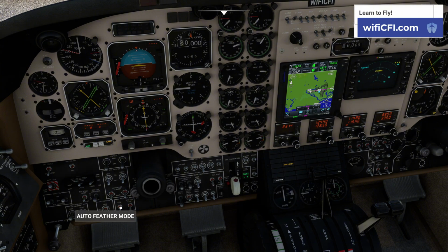Okay. Next one, we're going to go ahead and do the same thing again. So we're going to hold this, and then we're going to do it with our right throttle. Bring it up. We should feel the rudder boost kick on our feet. It's holding about that 1,700, so that looks good. We're not over torquing it. We're going to let go of the test. It should go up and not go above the red line. That looks excellent. So let's go ahead now and bring this guy back to our idle.